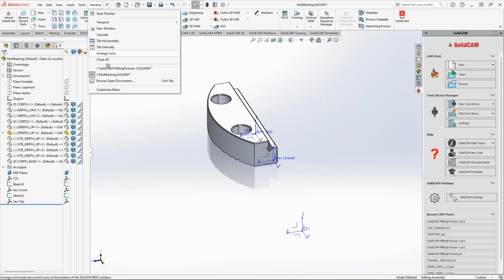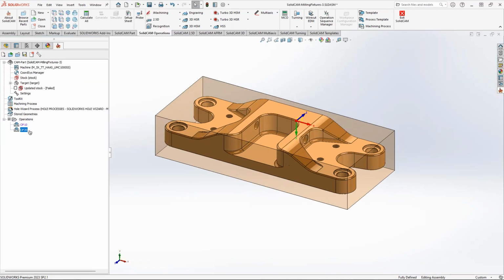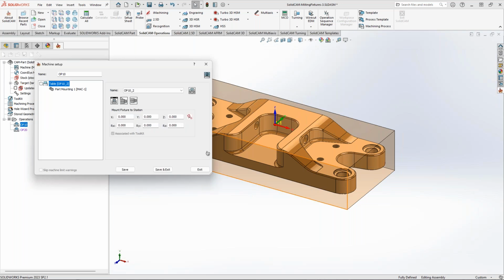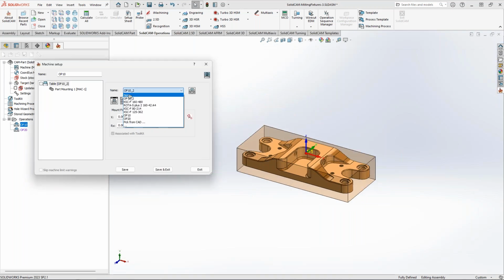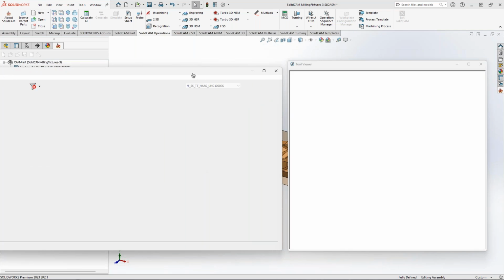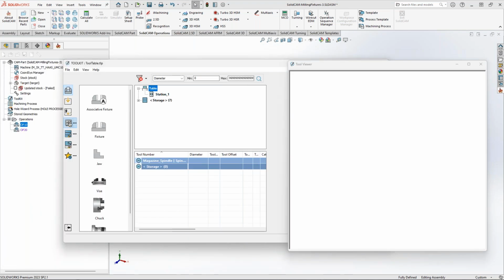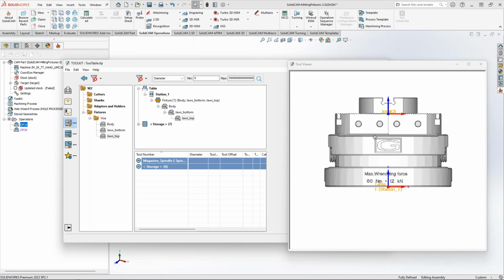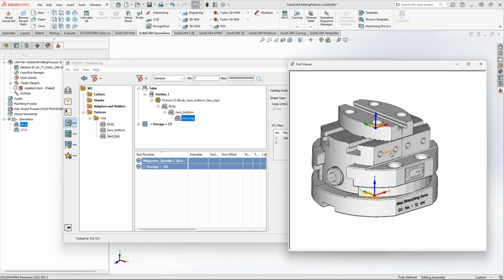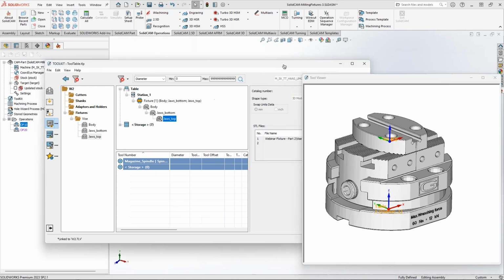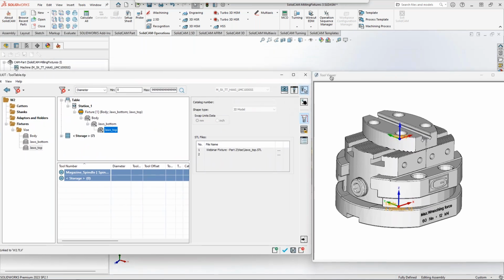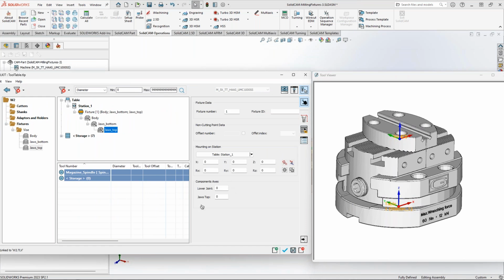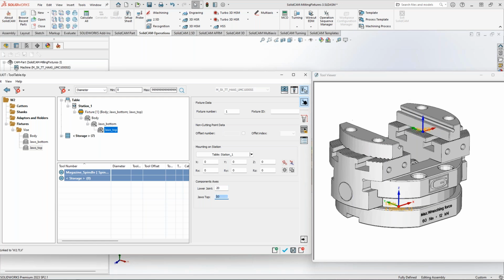Right, now let's use it in SolidCAM. I have here my first setup, and let's try to use it. Click on None, and let's start from the beginning. I have my table station. I open my vise. I'm going to put the body, jaws bottom, jaws top. I hope I didn't forget something. There we go. Voila, it's perfect. I can also move the axis that I created, and I have it over here. So all that I defined is my lower joint, and it also moved the upper joint.